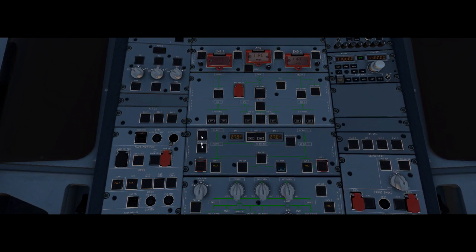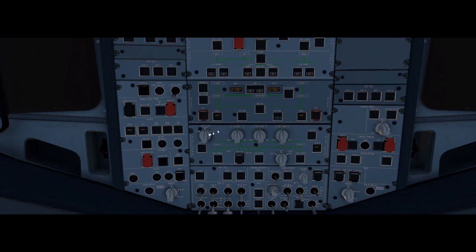So you've got your commercial signs, galley and cabin signs. It's really quite straightforward. Generator 1, APU, bus tie, external power, Gen 2, and the IDG2, IDG1. Coming down further in the centre here, you've got your pack flows, cockpit, forward cabin, aft cabin, hot air, packs, all the usual stuff. And of course, with the Airbus, if it's not lit up, then it's on. So these that are not lit up are on.